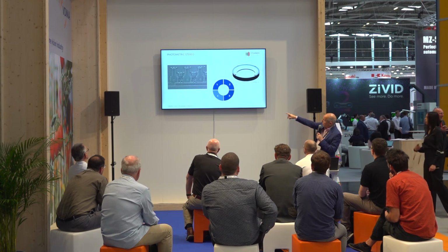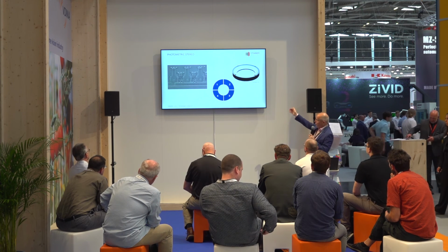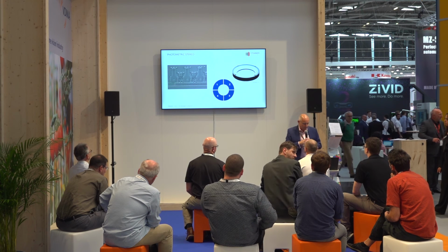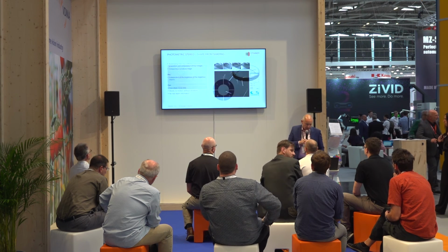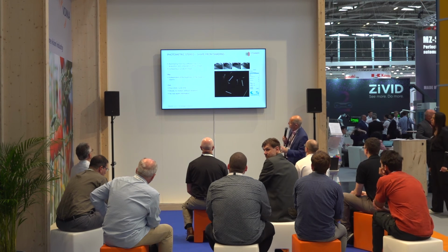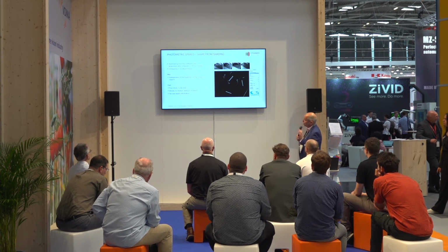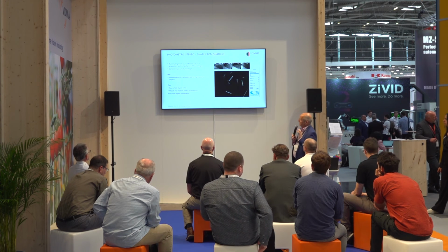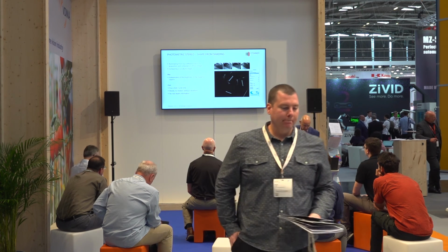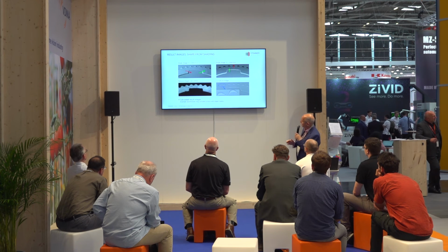So if we actually see here, we grab the light, fire lights in 4 different directions, and then we process that data to create the images that we want to get. And what this gives us is independence from the brightness of the inspection objects. The drawback is it's normally stationary, I'll come on to that in a minute. The cycle time takes time, but you don't get depth information, you get surface information. And this gives you an idea of the images that we've got.